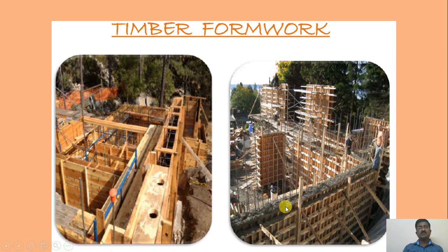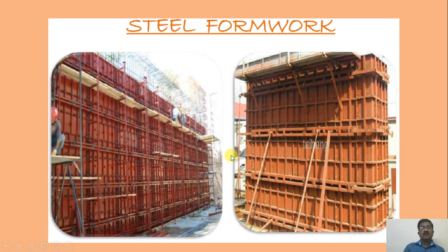Okay, so these are the various pictures you can see where types of this former can be observed. You can see how the timber is used here for a former purpose. So here you can place the concrete. These are the various planks which are used. These are the strengthening studs. Also these planks are placed here to avoid the shape change of that. So you can see everywhere you can find the timber in this. Then steel.